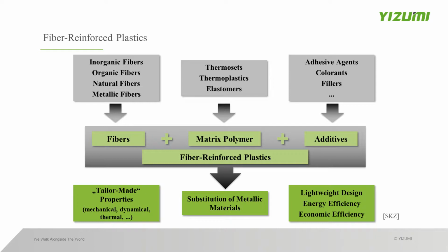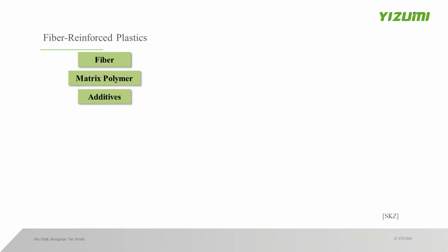We have calculated for energy and economic reasons. We want to use some cheaper material with fiber, not very high cost thermoplastic, like we want to use PP with glass fiber instead of PA66. This is also obvious.